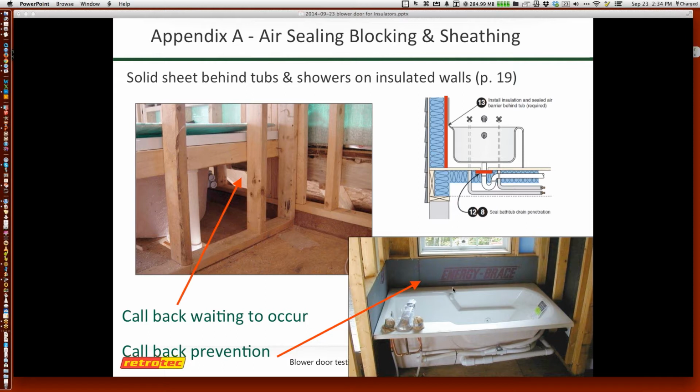And the one that's always a challenge is the tub and the plumbers in general, because why we ever let them use a Sawzall, I don't know, because they can create some massive openings for some very small pieces of pipe. So for those of you that are doing air sealing and you're doing insulation, these are the things that are commonly associated with one of the challenges. The plumbers are usually the first in, sometimes after the HVAC contractor, but this is one of the things that has to show up. So now I actually have an air barrier and some insulation.